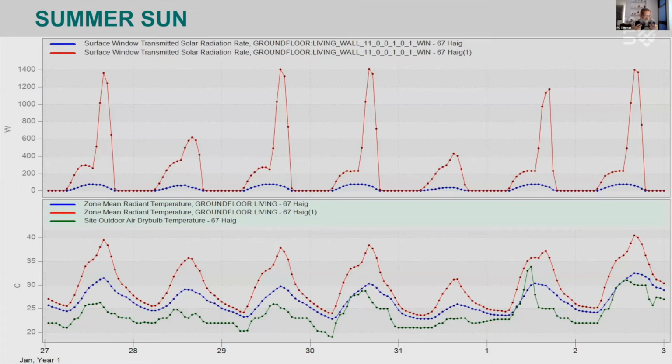Okay, so what I feel is my space starts to cook because the sun comes in through the windows. That shortwave radiation comes in, hits something, becomes long wave radiation, or infrared radiation, and that's not transparent to the glass. It travels out much more slowly. So I start to store heat, right?